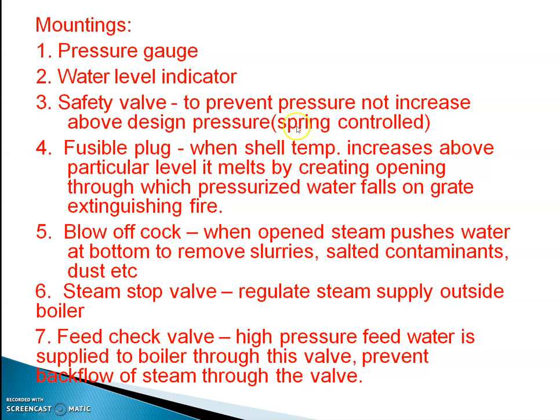spring controlled. For example, in a pressure cooker we also use a safety valve. If high steam is produced, the whistle will release it, and the same concept applies to the boiler. With the fusible plug, when the shell temperature increases above a particular level, it melts, creating an opening through which pressurized water falls on the grate and extinguishes the fire.